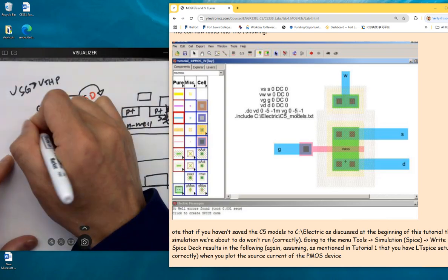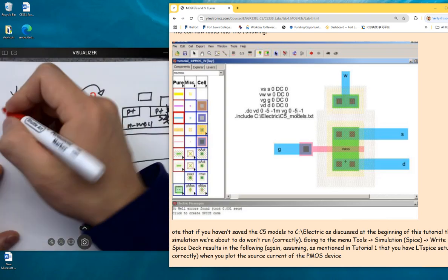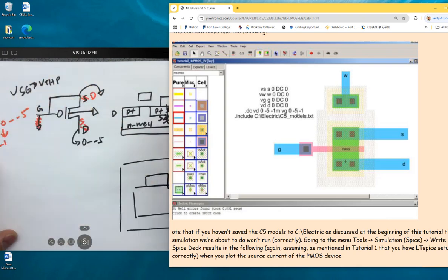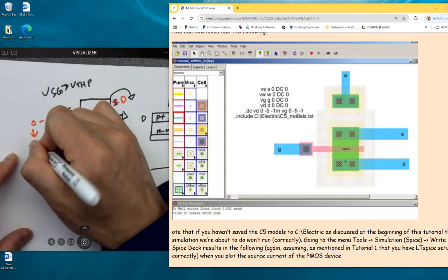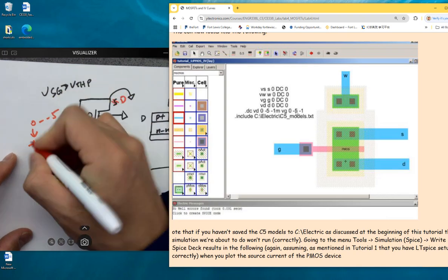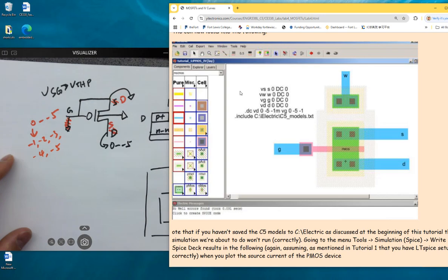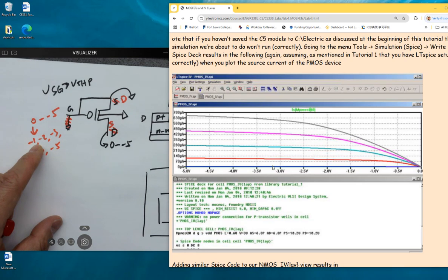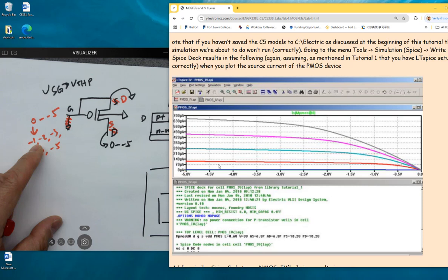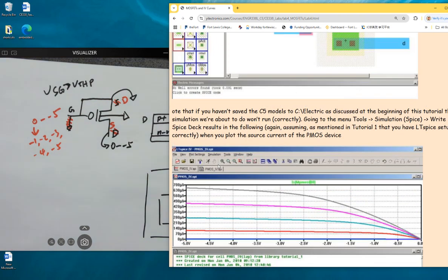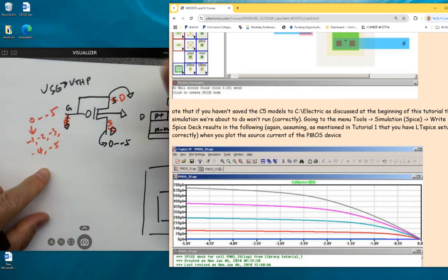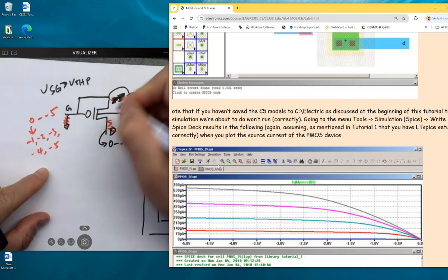So this one is actually not grounded. It changes from 0 to -5 volts, with a step of -1 volts. So it's basically -1, -2, -3, -4, and -5 for these 5 curves. 1, 2, 3, 4. 5 is over here. It's overlapping with here, which I think is -1. It's in the cutoff region. So in that case, this actually works. We don't have to change it back. But it's good to know it's symmetrical.